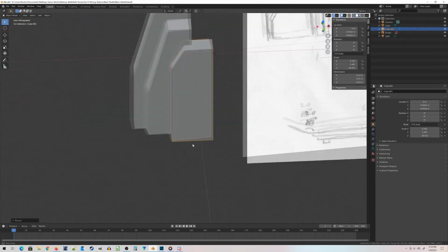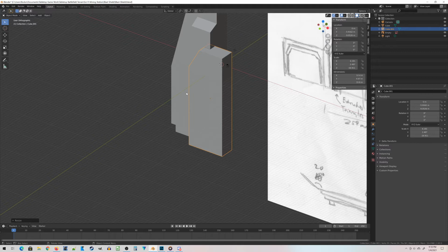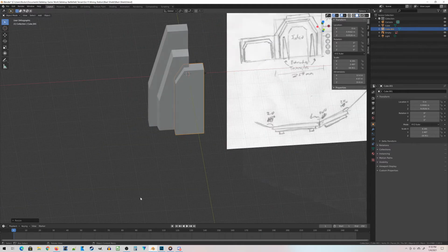front. Because the operation we're about to do is called a Boolean operation. And if it's not sticking out of the mesh in all dimensions, you're going to get a different result than what you expect. Maybe you want that sometimes, but in this case where I'm trying to cut a half inset in here, I don't want that.